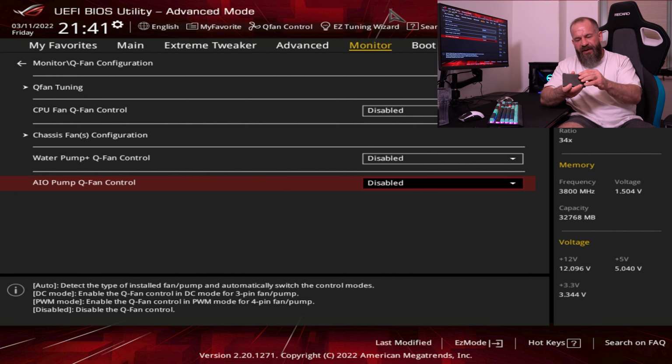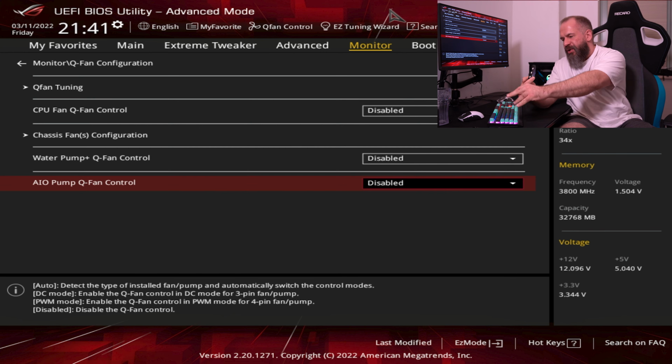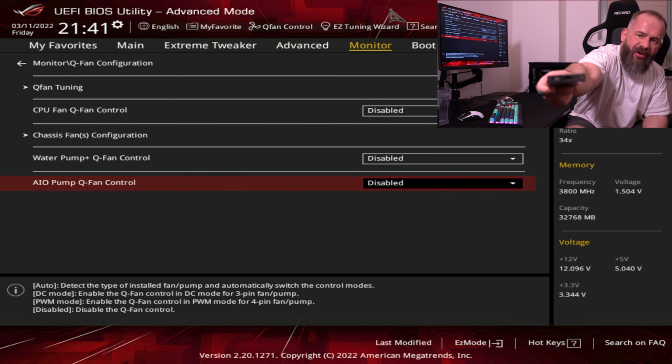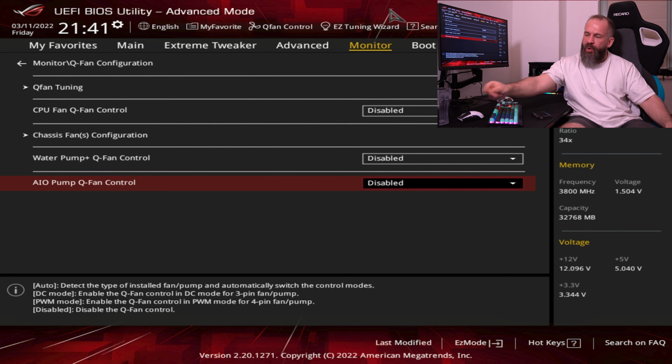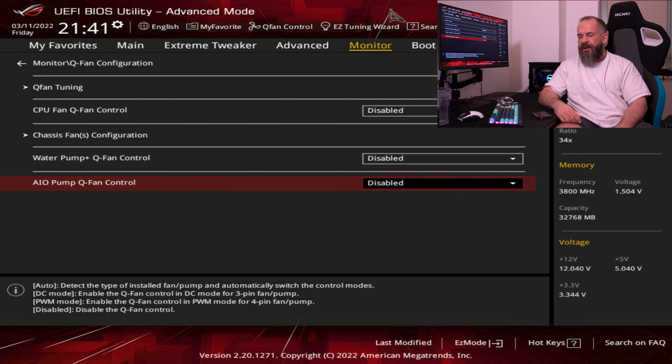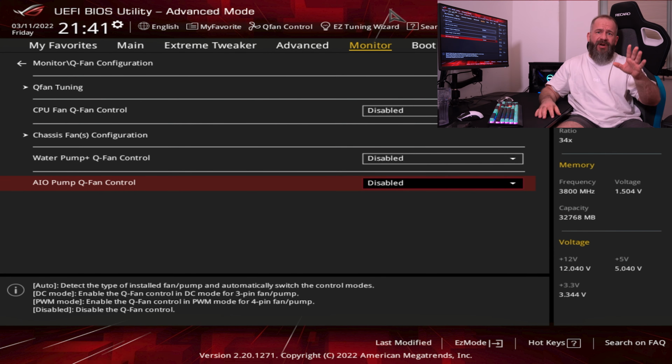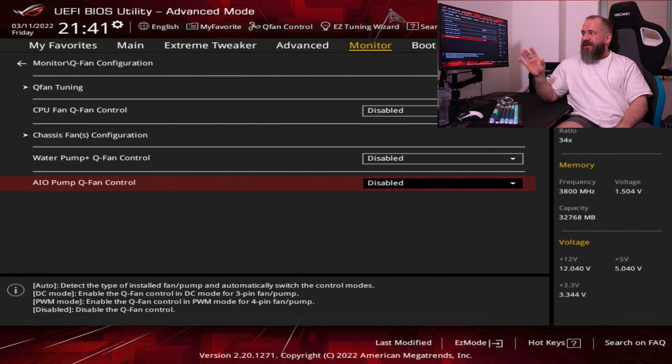I just seeked out this one. This is from my Asus Extreme, and as long as it's not a real powered one, with a real external power connector and a real USB control, so you have a real good external power source with more than 12 volt or with 12 volt and a high current, don't do this. Those ones built into your 150, 200 US dollar or euro tower are mostly not good. On high ends, they're okay, but don't do it. Just stick with your mainboard, motherboard settings and use the control.